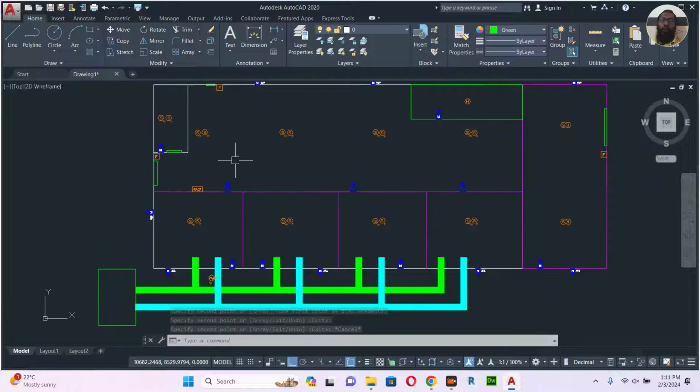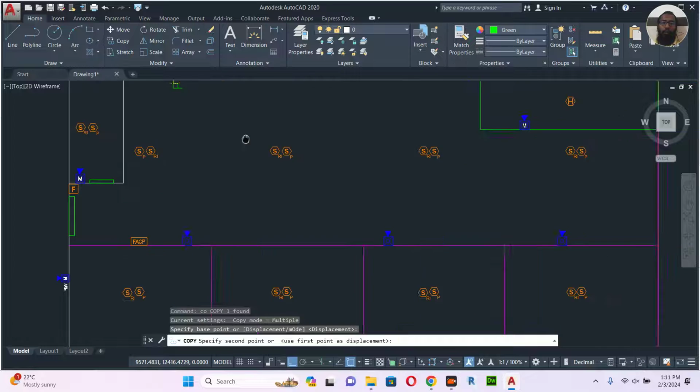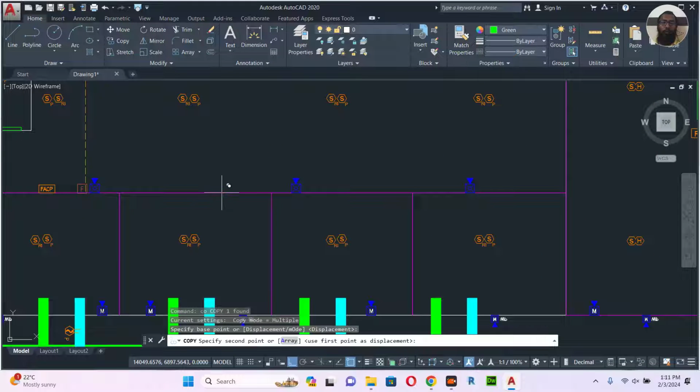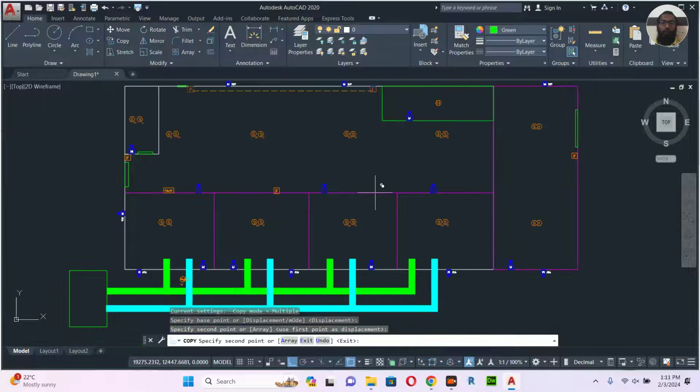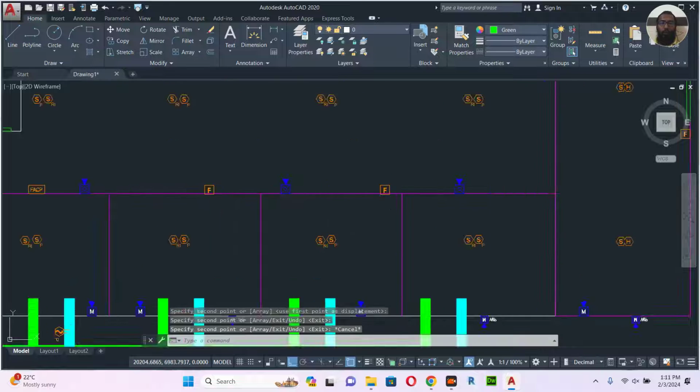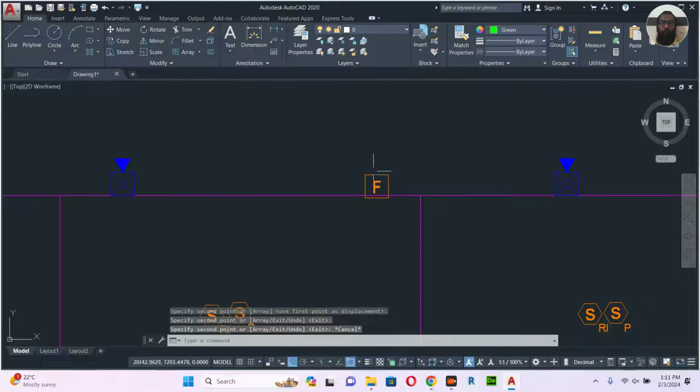Okay, now I have put some detectors above the ceiling, and some manual call points. Because this is very far, I need one here also and one here. So anyone coming outside of the room can use this one.